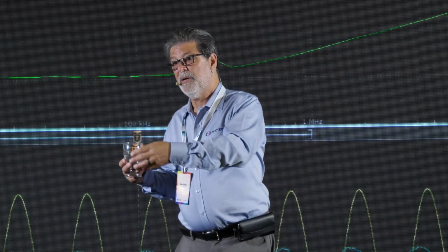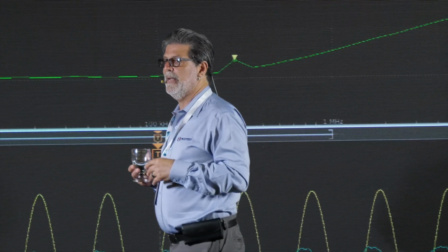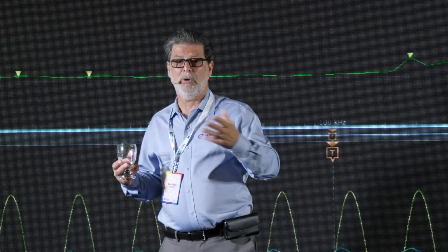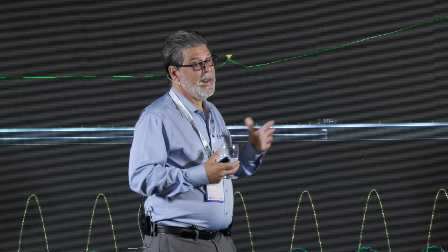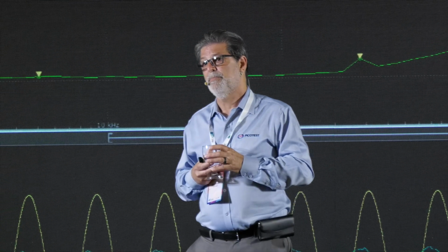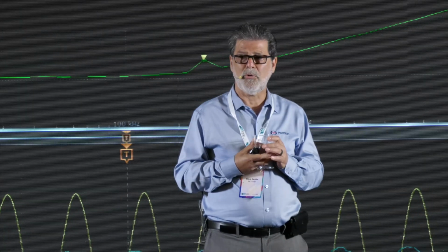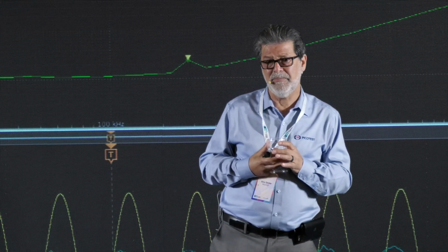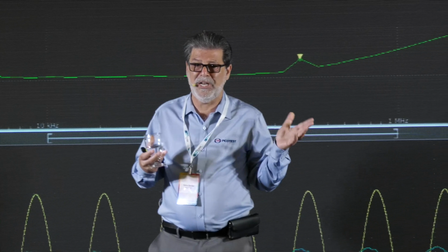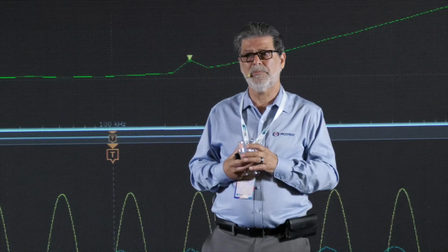and to guarantee that the chip gets the voltage that it likes. So what does it mean that the resistance is too high? The resistance has to be where it needs to be in order to accommodate the voltage ripple, the dynamic range, and all of the other things, the high-speed currents. And it's a relative thing. I have customers now that have single chip ASICs at above 1,000 amps, with 30 microohm power rails. I have one customer who's going to hit 2,000 amps in a single ASIC next year, with a 12 microohm power rail. When you get there, it's challenging. It's challenging to measure and it's challenging to design for. The average chip like that has maybe 2,000 decoupling capacitors per chip. It's crazy. But 12 microohms is a really small number.